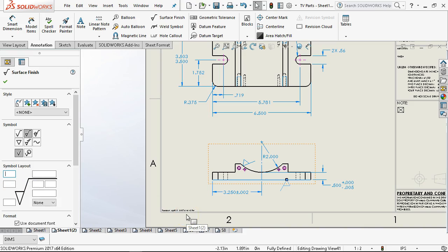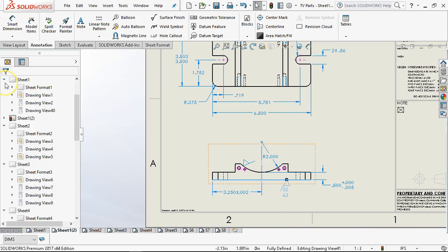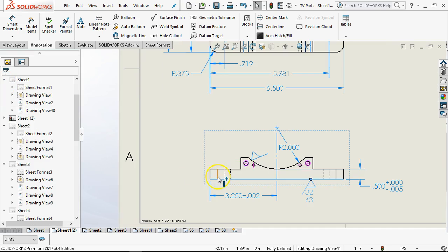The importance of giving it an upper and lower is if you don't want a finer finish, so O-ring surfaces that need to bite into the wall a little bit, you would want to limit the upper and lower, 63 to 32. Otherwise, it's assumed that if I can go finer than 63, or finer than 32, or finer than 16, I'm going to from the machining process.